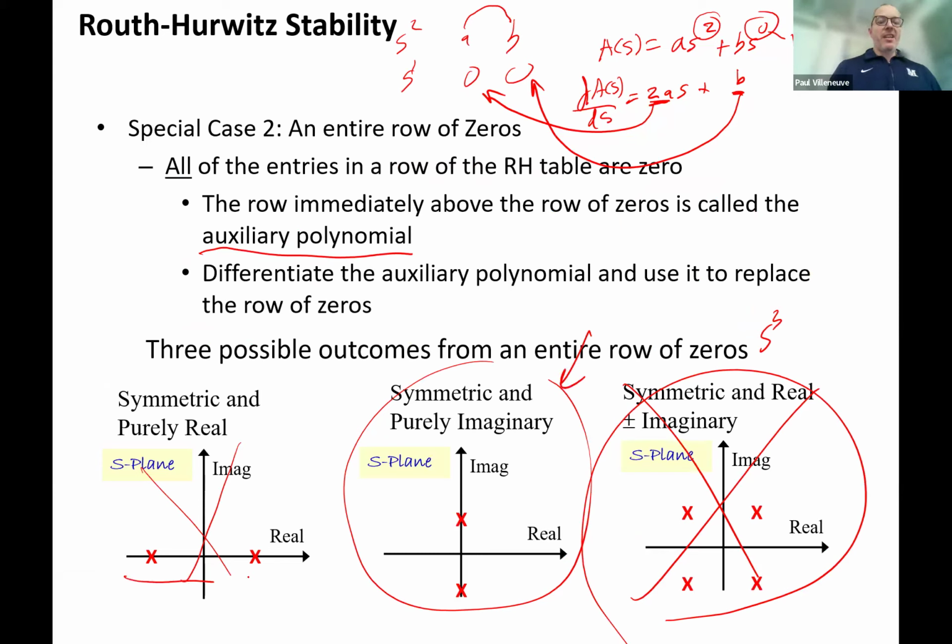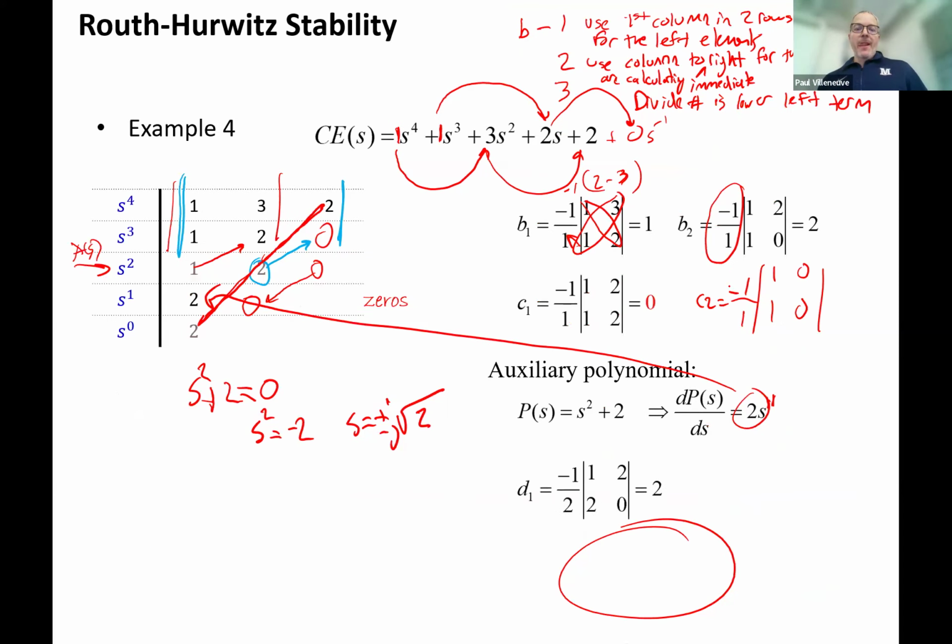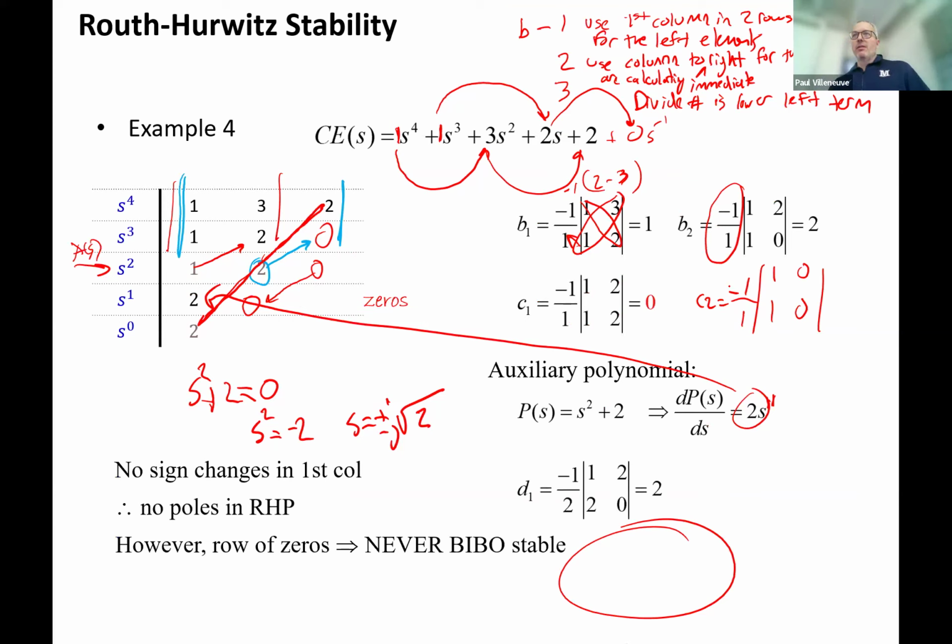If you have these 2, it would indicate you've got a sign change. So this would basically take care of that case. Same thing over here: you'd have a sign change, and you'd also have an auxiliary polynomial way out over there. So the only one I've ever seen is the middle one, where you can use the auxiliary polynomial to tell me what the actual complex roots are.